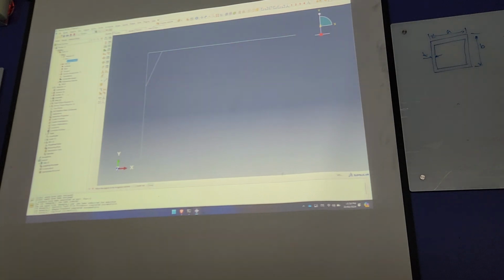And I'm saying, okay, I'm putting beam section on them. So you can see here, that's sort of lime green, and this one here is sort of still gray. That's where my truss is going to be. So again, selecting that, done. Rather than choosing beam, I use truss. Okay, now everything is there.